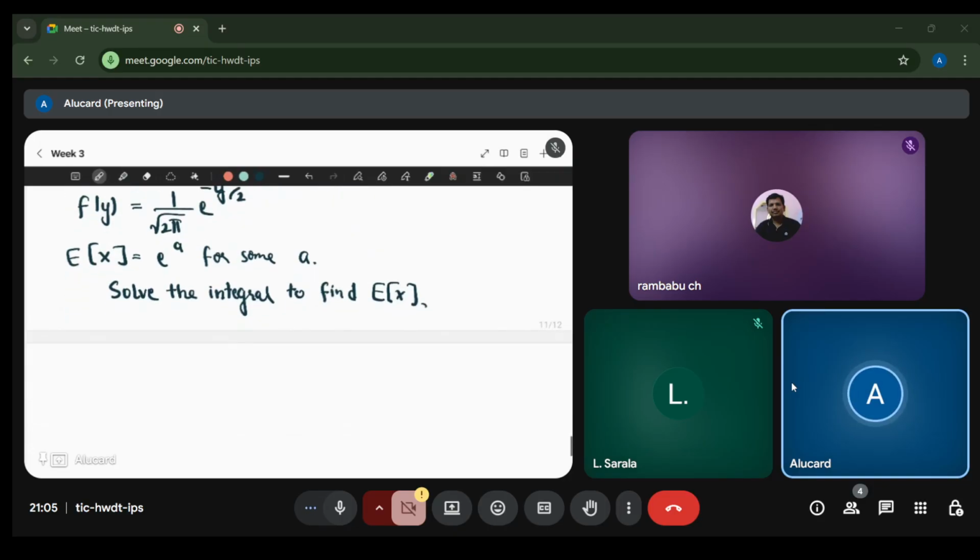Then question 19 says a mobile phone receiver operates at 2 gigahertz in a bandwidth of 200 kilohertz at 300 Kelvin and has a noise figure 6 dB. The receiver is present on the cell edge and a minimum 4 dB SNR is required for reliable communication.